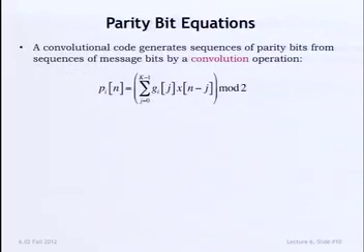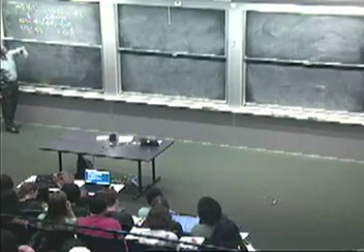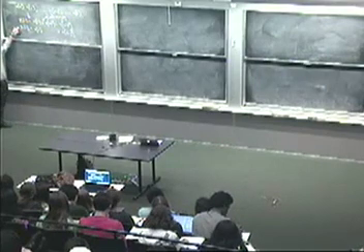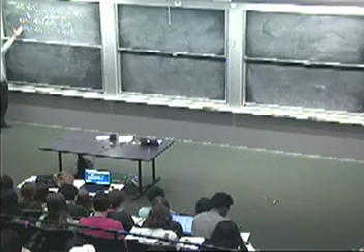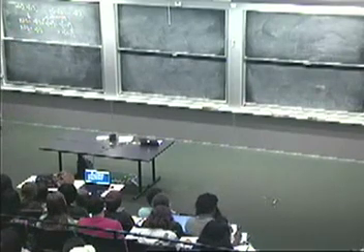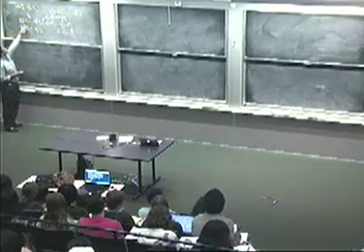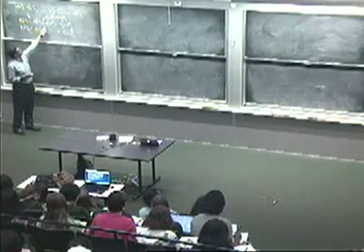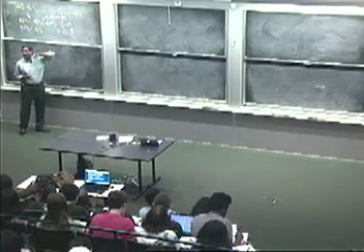So let me just put up an equation that explains why this is called a convolutional code. It turns out that expressions of this type, where you take a data stream coming in and generate new data streams of this form, it turns out that the operation that's being carried out here is something referred to as convolution. So in general, what is P0 of n? It's some weighted combination of x at the current time, x1 time step back, x2 time steps back.